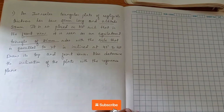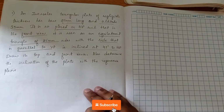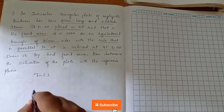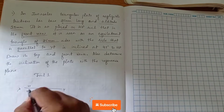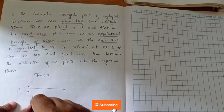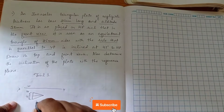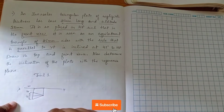So before going to the problem, first we have to identify whether it is resting on the HP plane or on the VP plane. For that I'll be doing a trial. In trial 1, say this is our XY, VP, HP. Say we have constructed it placed on the HP plane, what happens? Say this is our isosceles triangle. Consider this is the altitude. This is the top view. So this is the front view.